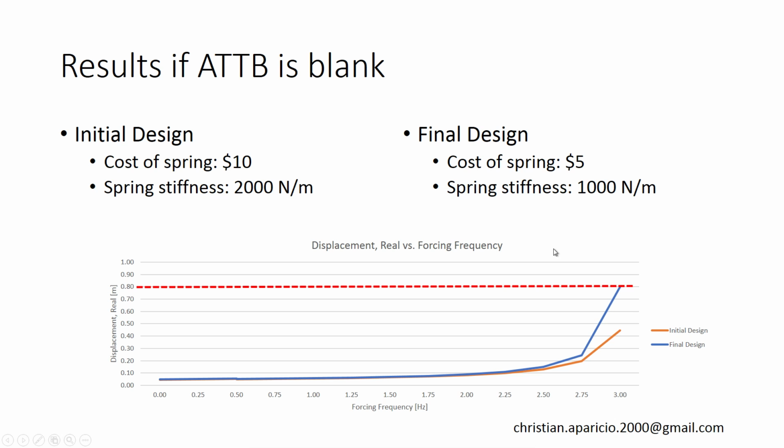So there you go. That's how you impose a design constraint if you're performing a frequency response analysis. In this case, we did it for displacements. In the next few videos, I explain how to do this for element force, element stress, constraint force, and the rest. My YouTube channel has dozens of other videos walking you through how to perform optimization with MSC Nastran.